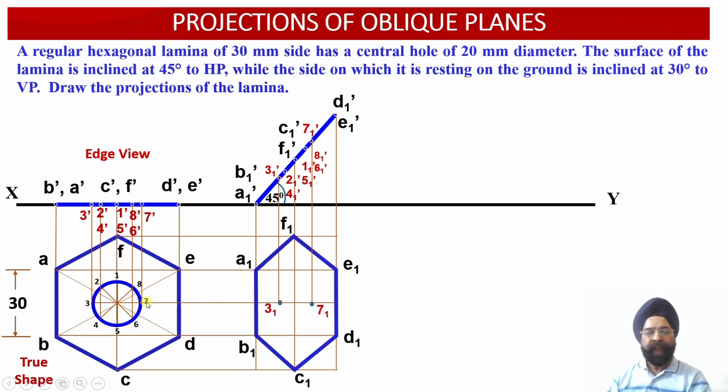So now we can see 3 and 7. These are the 2 points which are going to yield a single horizontal line. So this is the single horizontal projection line which we have drawn through the points 3 and 7. So let us evaluate the location of the vertical projectors which will be drawn through the points 3-1 dash and 7-1 dash. So the 3-1 dash point lies here. If we draw a vertical projector downwards, we find that the intersection of this vertical projector drawn through the point 3-1 dash with the horizontal projector drawn through the point 3 of the plan projection view occurs over here.